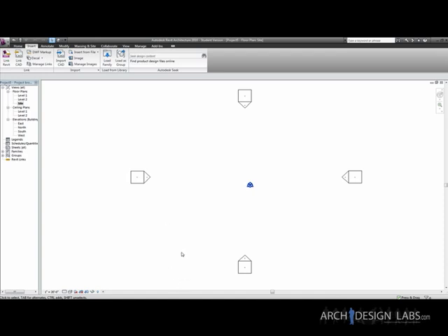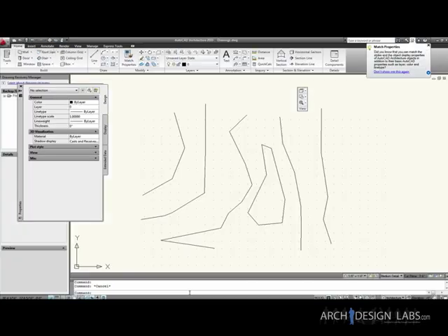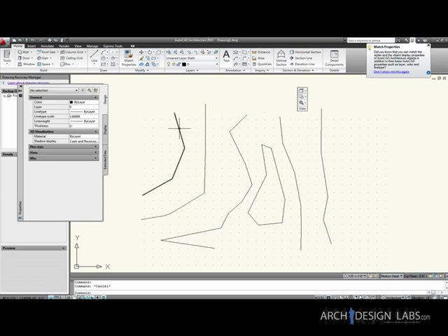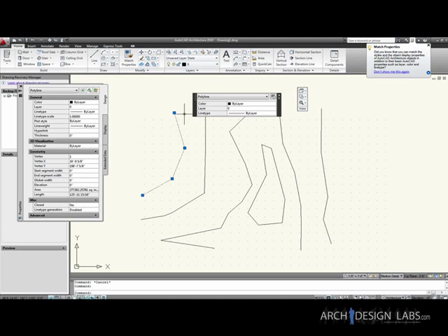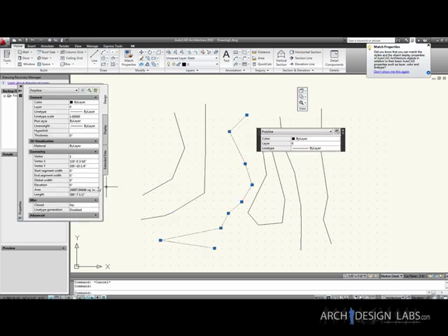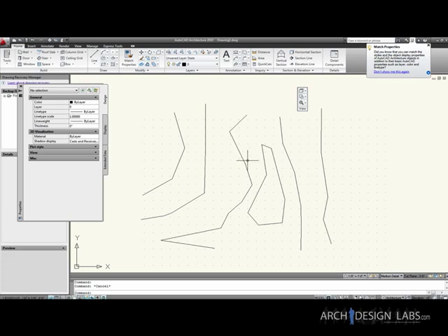So what you need to do first is make sure that your CAD drawing actually has elevations on it. I just made up some generic contour lines here, all polylines. If you look here in the properties of this line, it says the elevation is at 0, which is fine if that was a flat surface, but when they're all at 0, you're not really getting a clear reading of the topo surface. You're just getting lines. If you don't already have a 3D CAD drawing, and if you do, congratulations, you can just bring it straight in.